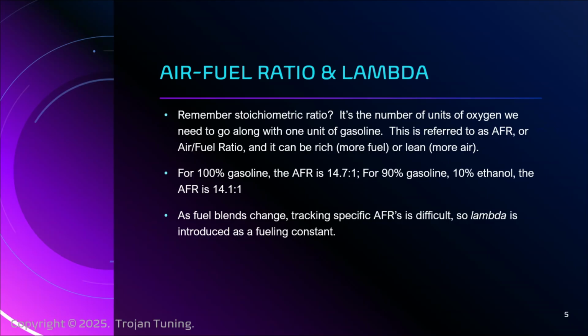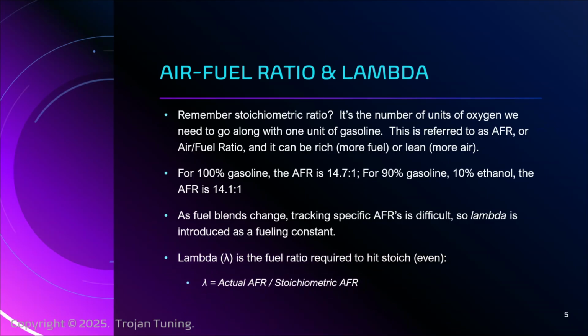And then let's imagine as well that you've got a 90-10 mix of gas in the car. You've got a quarter tank of it when you roll up to an E85 pump where you're pushing in a ratio of unknown, right? Could be 66, could be 70, could be 58% ethanol, right? And that hits gas that's already at a certain ratio, right? You can see quickly the math becomes very cumbersome, and it's a real bear. And so that AFR would be constantly drifting as the fuel composition changes, and that would be a real pain in the ass, right? So lambda is something we use.